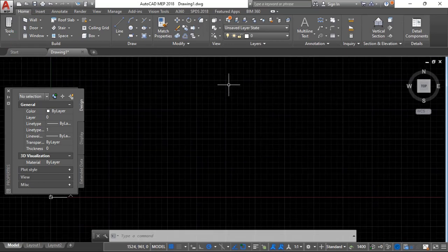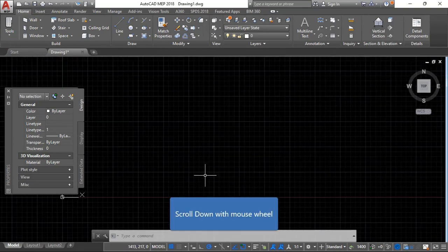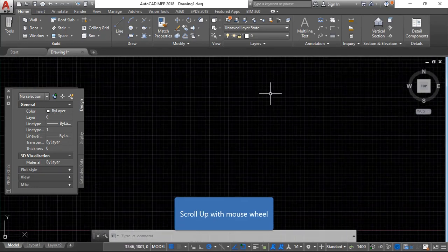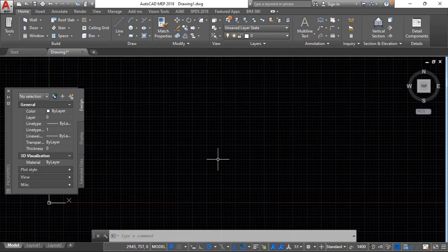So you can make that house look whichever way you want, but usually in the plan, the south elevation is assumed to be the front of the house. Whichever way you are drawing, make sure whatever is the front should be below, especially the living room, dining area, and so on.